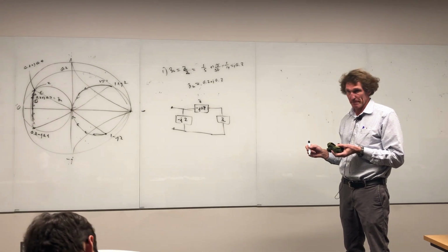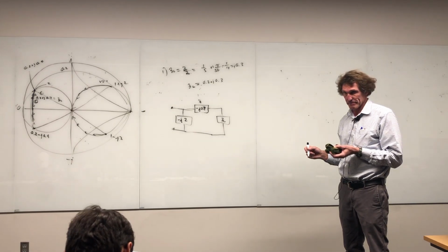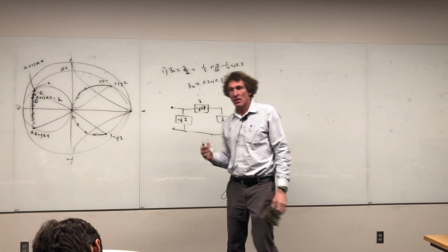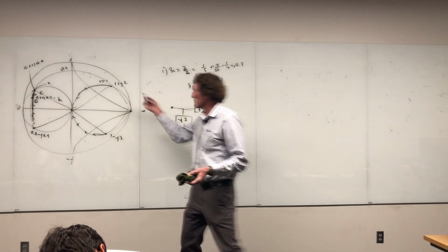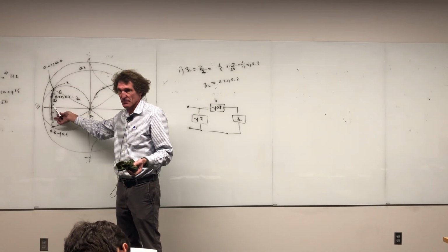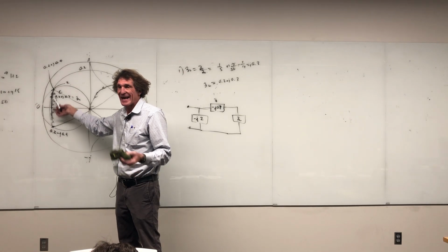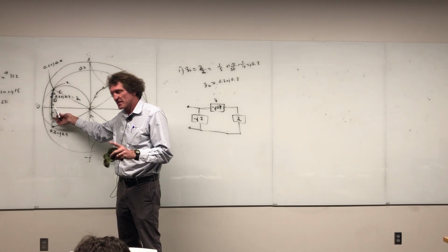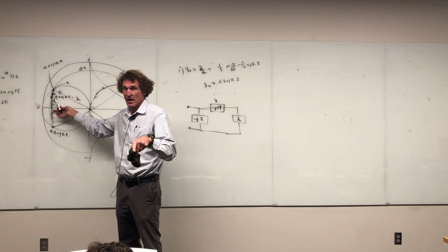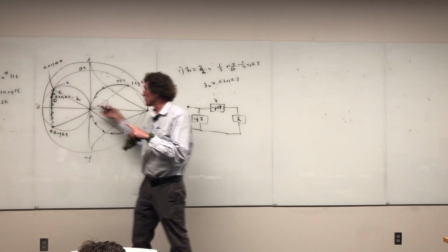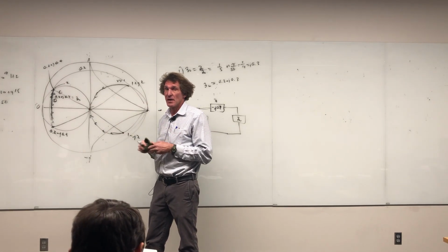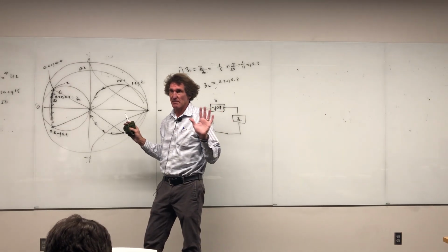Not the preferred, yeah? How do we know when the components are in parallel or series? Well, shunt is parallel, all right? When you start in the impedance domain, anything you add is in series. And then when you reflect it into the admittance domain, anything you add is in parallel or shunt. Shunt and parallel have exactly the same meaning.